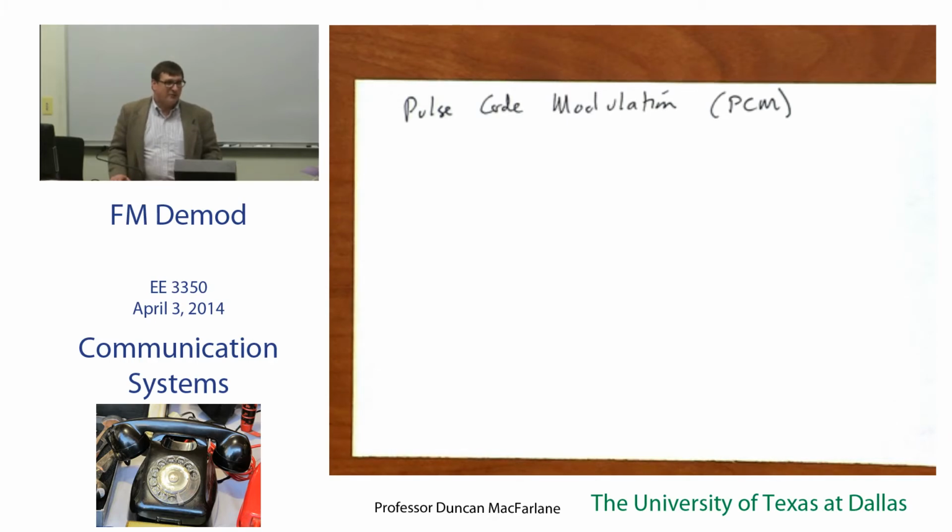You might ask, why did the optics folks take a step backwards from digital to analog? The answer is the cost of that digital regen was so high when you multiplied it by the large number of wavelengths. It turned out to be cheaper to take the hit on noise and then work really hard to control your noise. And so you could go further and further.